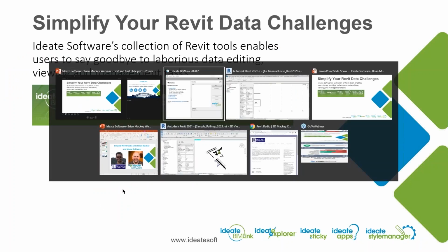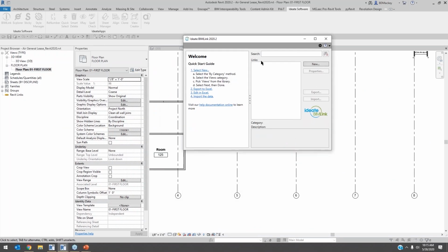They said, we did a tenant improvement, and what we really needed to do is have another tenant improvement for a different client on the same project. So they're Revit linking in the entire building, and then they're doing the little tenant improvement in the one area. It's like, well, we just did tenant A, now we're doing tenant B, but we're going to use all the exact same sheets. So they started a new project to link that in. They did not want to do a save as from the old tenant improvement, but we had all that sheet information in there. So how can we start going through and getting into that?